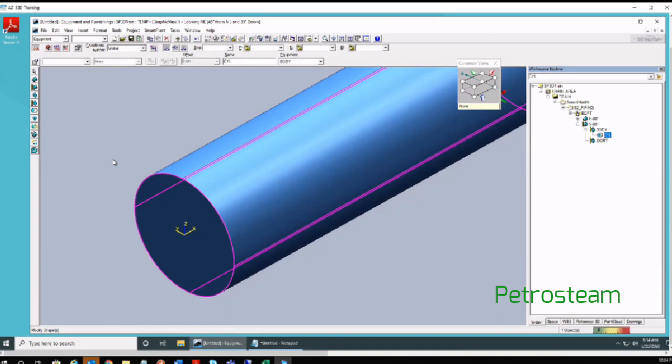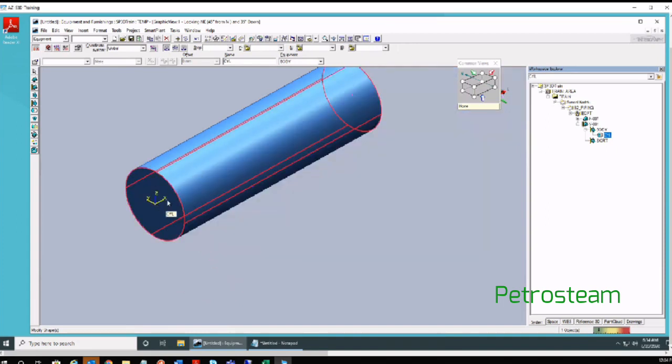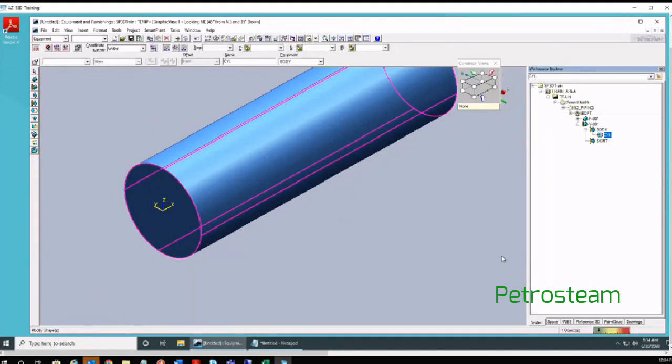And if you rotate now, it will rotate around the Z axis. My requirement is it should rotate vertical 90 degrees. That means it should rotate around the Y axis. So to activate the Y axis from Z, you can note down, use the up arrow mark on the keyboard. On the keyboard, right, left, up, down arrow marks are available near the numbers. Use the up arrow mark. I used it once.